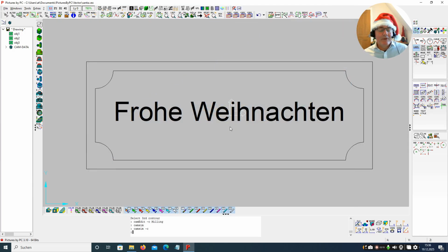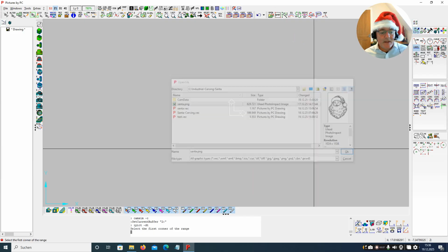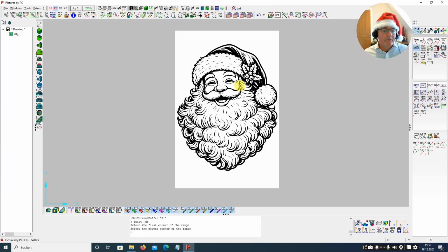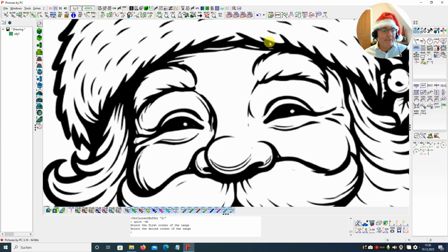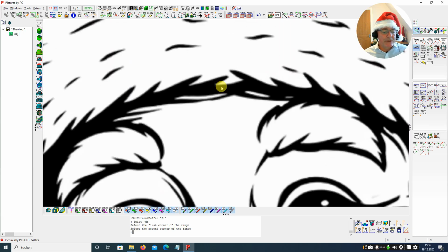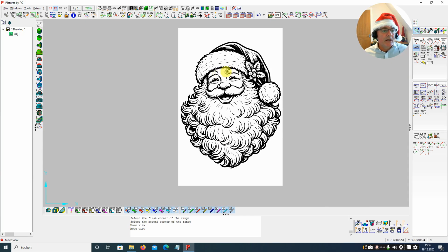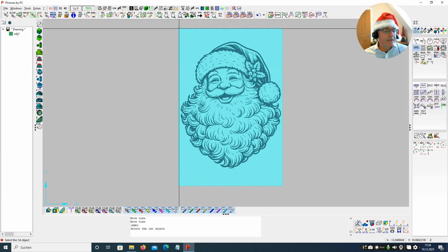The question we've got now is, where do we get the geometry from to machine? If we had a company logo, for example, we could import that as a vector format, or maybe possibly we get this as a bitmap. So let's look at bitmap vectorization. We've got Happy Santa here. In black and white, you can see the resolution is lousy. We've got some points on the bitmap. We'll see how these come across. Let's delete that and vectorize this.